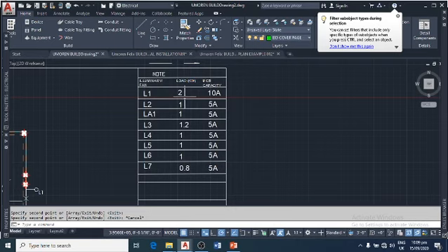We're using about 220 volts supply voltage. 2000 divided by 220 gives close to 8 point something ampere. So having anything less than 10 ampere, we're using a 10 ampere miniature circuit breaker. This implies that the rating there is greater than 5 and less than 10. That's why we're using L1, 2 kilowatts and a 10 ampere miniature circuit breaker.